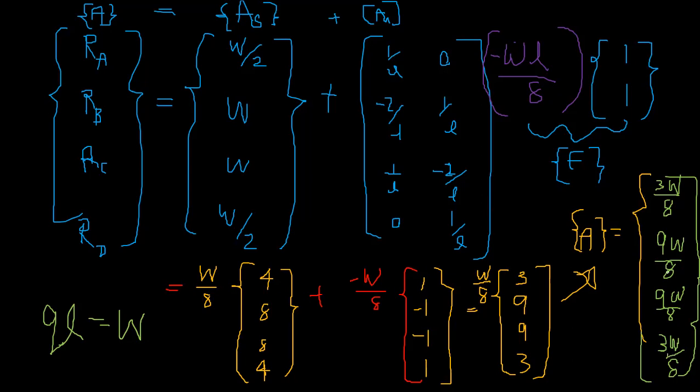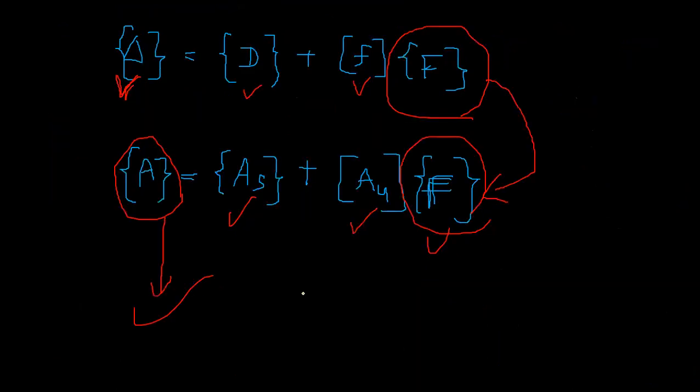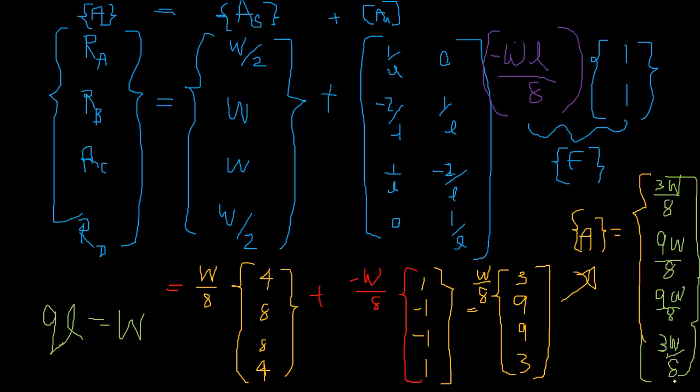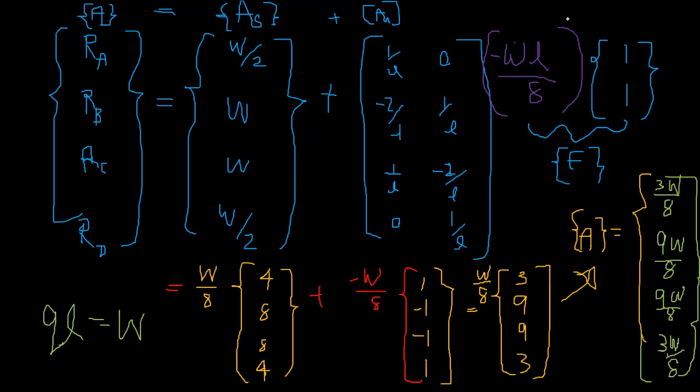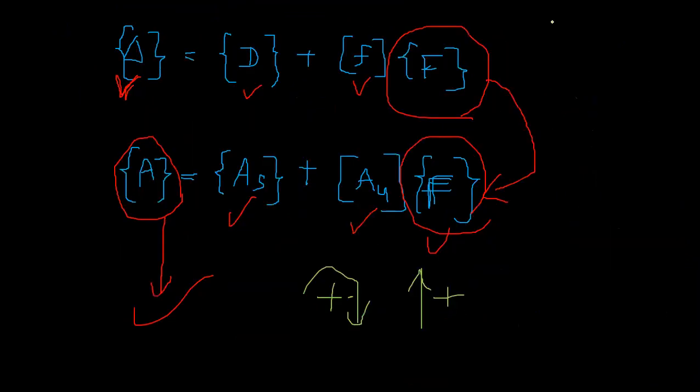So these are also positive, right? So we considered clockwise positive and upward forces positive, upward forces and displacement. So these forces are upward. That means these ended up as positive. So that means all the reactions are positive in the upward direction. And the moment we considered is negative, and that means anti-clockwise. So thank you.